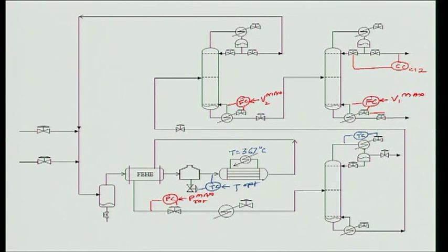Now that I have done that, what else will I do? Yeah, I need to tightly control the benzene leaking down the bottom. So to do that, I put this in. Economically important things, you see, I want tight control of this. However, boil up is max. Because boil up is maxed, this temperature cannot be controlled using boil up. So what are the options that I have? I can control it either using the feed or the reflux. Since the feed is closer, it will have a faster impact. So I control temperature this way.